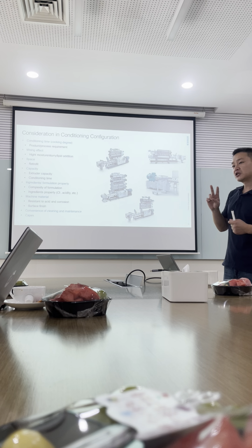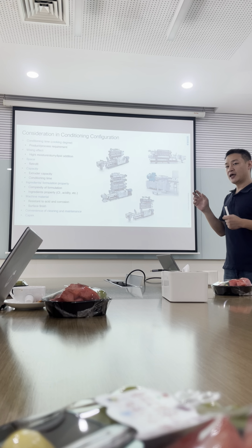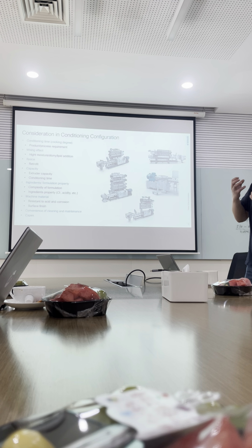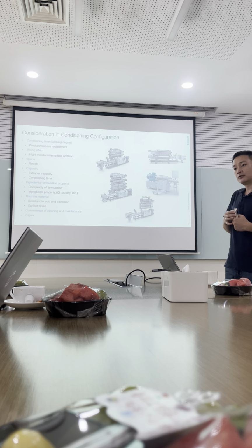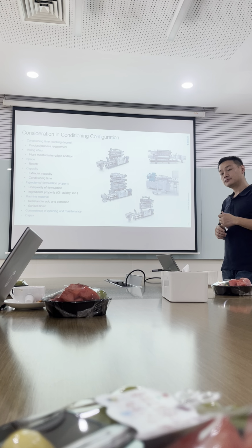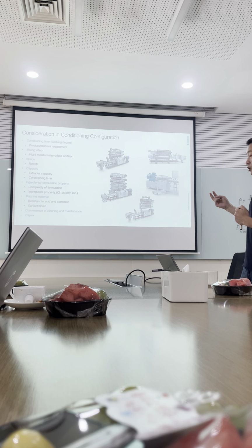It's almost double that of the DDC used in aqua feed, because they want very good mixing homogeneity, so they increase the speed of the DDC. And in Buhler, we also have two types of DDC. One is low speed, and the other is high speed.